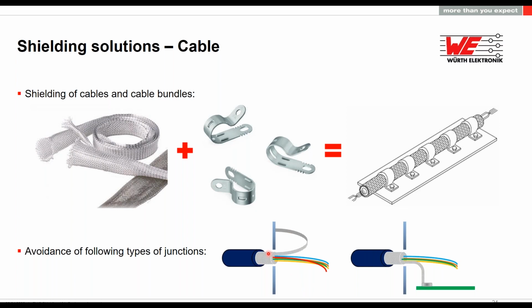Why? Because when we are going higher in frequency, or there are signals of high frequency going to this shield or to this part, this is behaving like an inductor. And when this is behaving like it's creating a parasitic inductance. This parasitic inductance, it's able to create noise when we're going high in frequency. And this noise goes through all the shield of the cable.